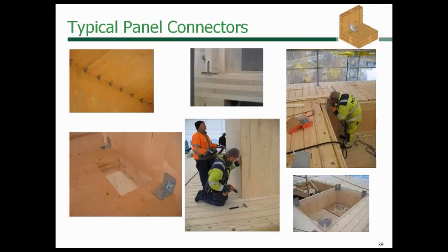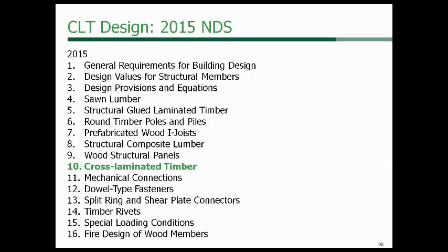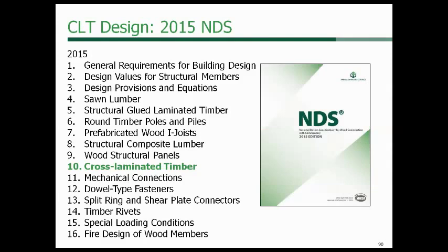So you can see here the panels being connected on a project. It doesn't require any special tools beyond a screw gun, so you don't have to have any additional tradesmen on the site. Now, for the first time ever in 2015, cross-laminated timber has its own chapter in the NDS. It is in Chapter 10.